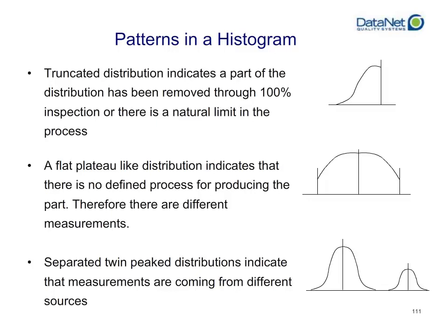Going forward, to be able to do proper process control, to be able to statistically control each line, you need to separate the two processes. You need to find out what those two processes actually are and separate them. Now, it doesn't just necessarily mean twin peaks. You could have triple peaks or quad peaks. You could have multiple peaks indicating that you are mixing together measurement data that should not be combined.